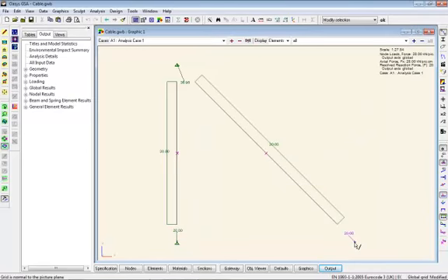You see now this 20 kilonewton tension load has gone up this cable, round the corner, round essentially a pulley, and then down the next one. So you get a reaction of 20 there, and a much larger reaction at that point there. This can be very useful in GSA, but if it's misused, can produce some very strange results. So very powerful, but use with caution.